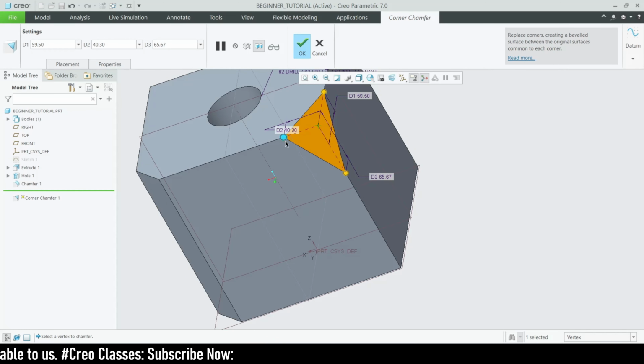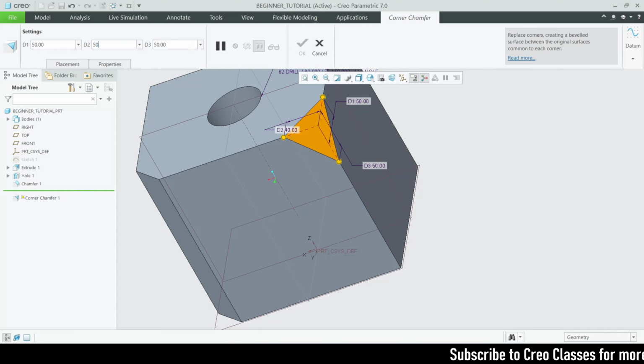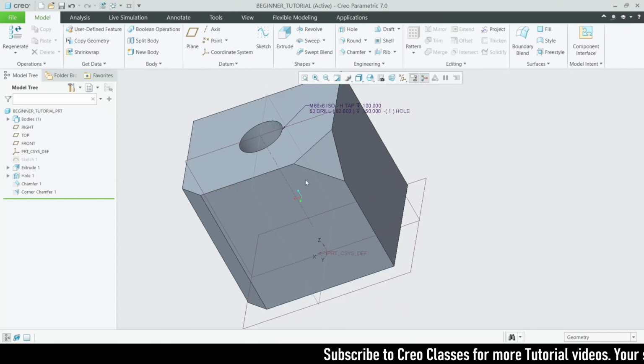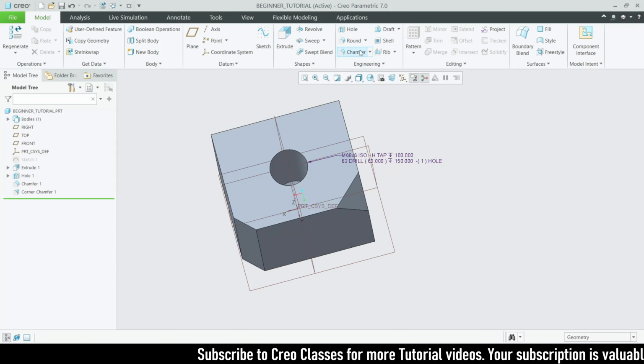You can also drag like this for each and every side, or else you can have separate values like 50, 40, or 30. Or else you can add the same value for all the sides so that it looks even. So this is how you can use this chamfer tool.